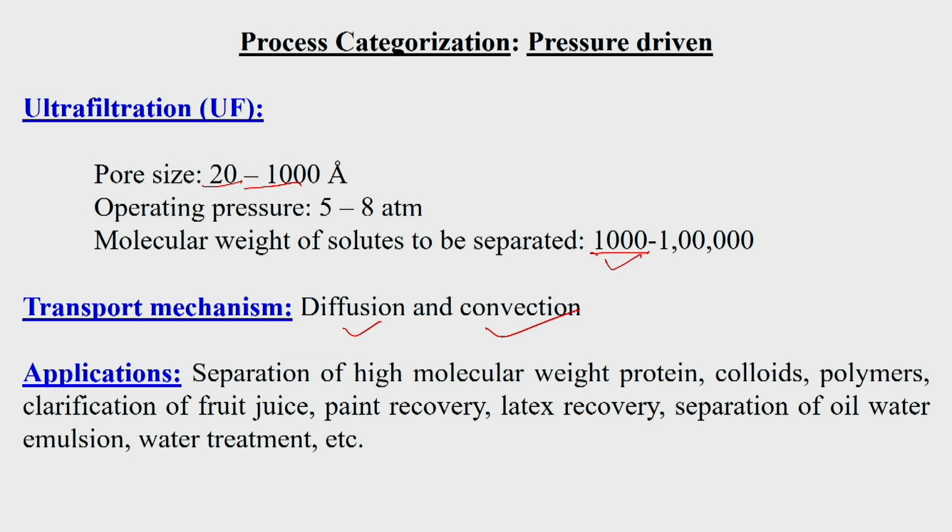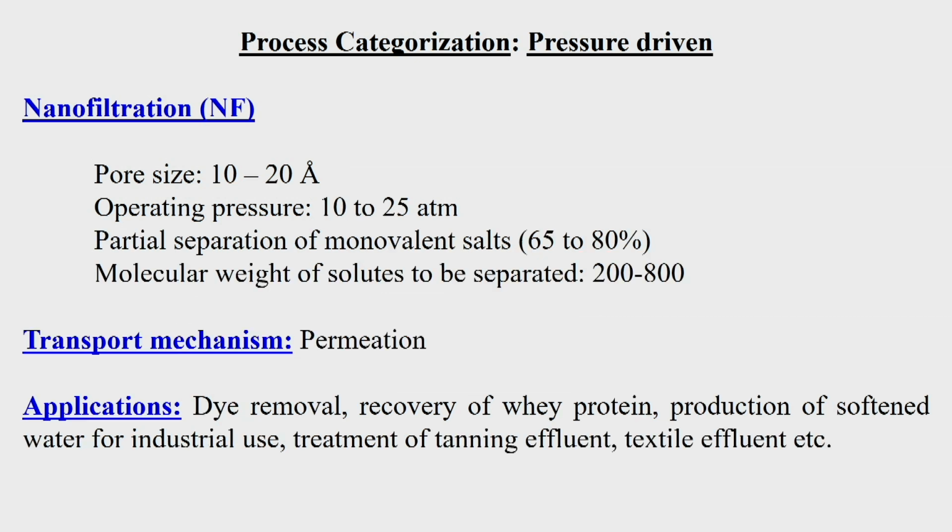So, separation of high molecular weight protein, colloids, polymers, clarification of fruit juice, then paint recovery, latex recovery, separation of oil from oily wastewater, then water treatment, wastewater treatment, and so many. Okay. Now, we will be discussing the nanofiltration membrane. Their pore size now becomes denser, only 10 to 20 angstrom, meaning in the nanofiltration range,